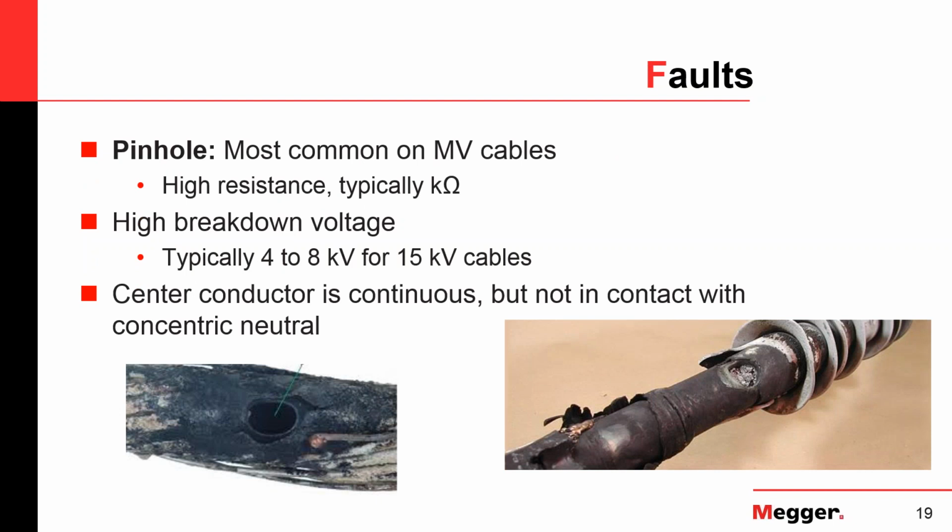So now let's talk about faults. You can classify the faults mainly by the resistance, but I wanted to take a little bit of a more practical approach. The most common fault in typical medium voltage cables is a pinhole fault. It's a high resistance fault that is at least in the kilo ohms.